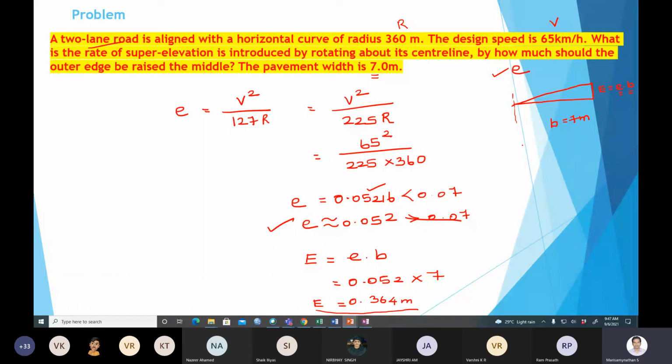That super elevation ultimately counters the effect produced by the centrifugal force. The centrifugal force causes skidding or overturning. These two issues happen due to the centrifugal force, with respect to the loss of friction and the super elevation. So to avoid this conflict and accidents, the super elevation is introduced on the field. So this is one simple problem showing how we provide the super elevation.